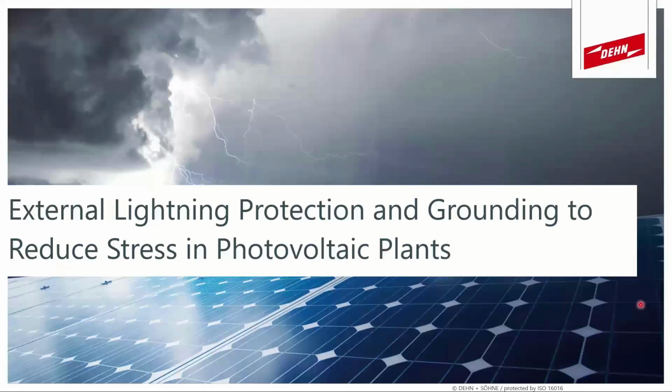So what I hope that you take away from this presentation today is an insight on how to incorporate planning for lightning protection into your complete PV plant design. Because this is often neglected, and it's extremely important to get this right from the beginning, as it works from the earthing system or the grounding system on the way up.